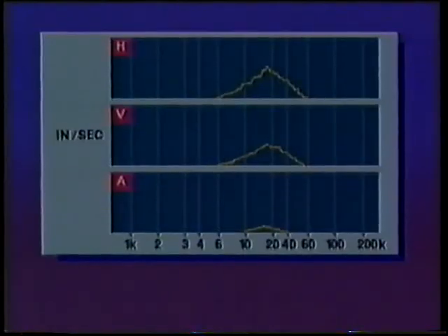Now let's look at another kind of machine component that causes high-frequency vibration: anti-friction bearings. The number of rolling elements in an anti-friction bearing affects the frequency of vibration. So, as anti-friction bearings wear, you'll typically see vibration amplitudes at high frequencies. These signatures can be distinguished from other types of vibration in 2 ways. The vibration amplitude tends to be fairly broad and doesn't usually occur at an exact multiple of RPM. This is due to the nature of the construction of rolling element bearings.